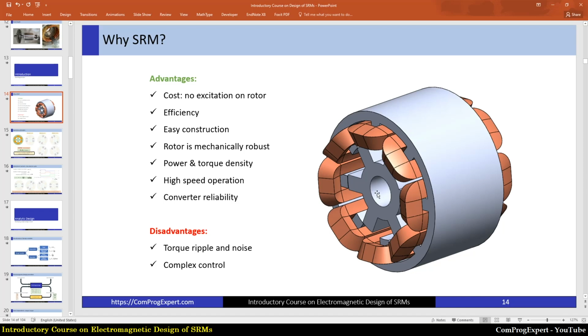But in this motor type, the total developed electric torque is only reluctance type, and in induction motor the torque is due to the interaction between the stator field and the rotor field, eddy current induced in the rotor cage of induction motor, and the operating principle is different.